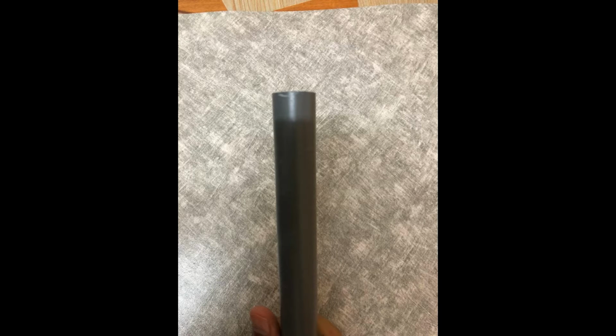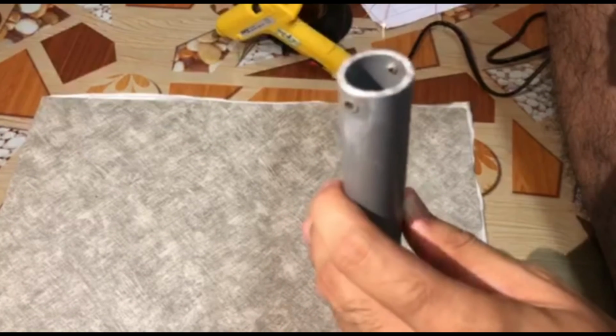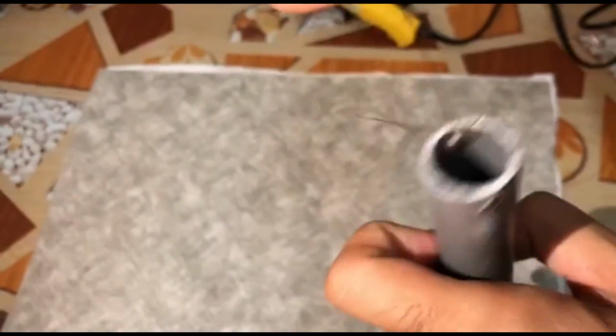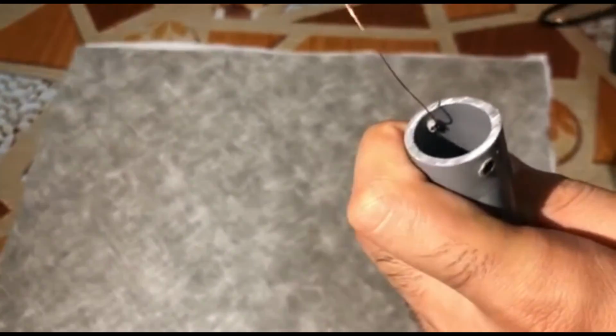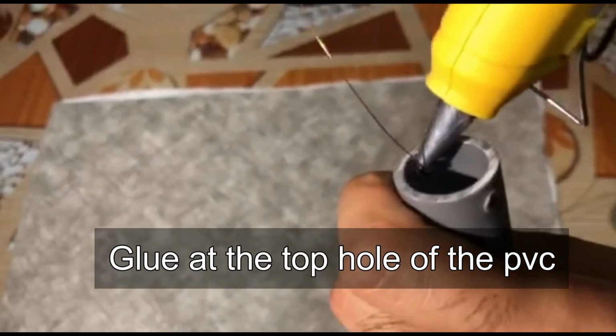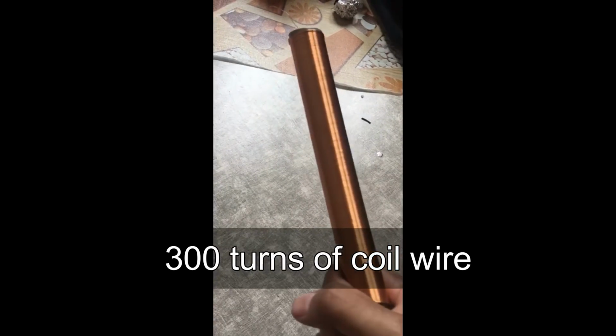The first thing is to take the 20 cm PVC and drill a tiny hole for the coil wire at the top of it. Insert the coil wire through the tiny hole of the PVC and glue it at the top hole of the PVC. Then we wrap the wire coil around the PVC, with a diameter of 3/4 inch, for a total of 300 turns.